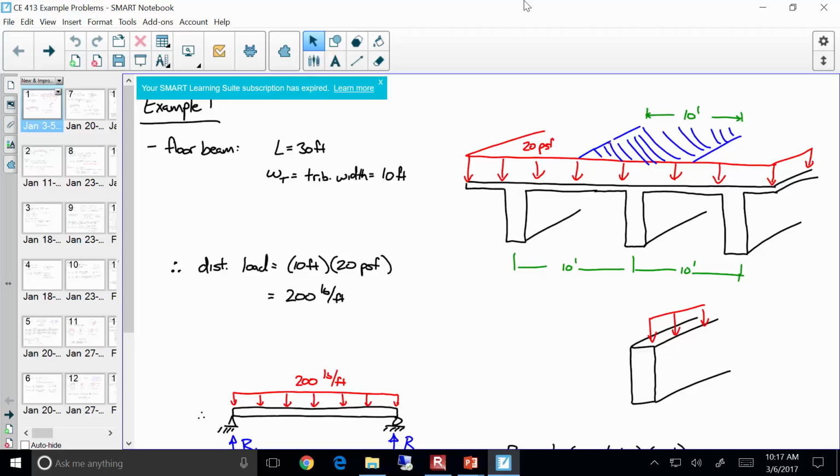Look, if you design a beam and you use 6 number 9s as opposed to 7 number 9s, yeah, the beam's going to be a little heavier. You'll never know it. It's not going to affect your design loads at all, really. We're talking a few pounds, on the order of kips. It doesn't matter. You okay with that? We can go through it if you want.